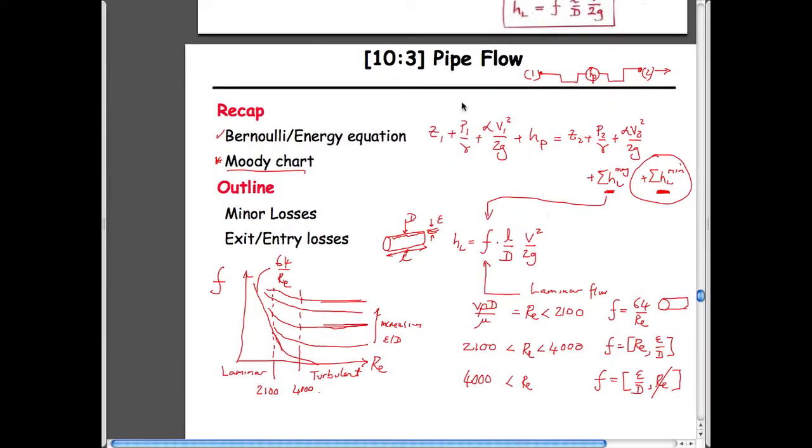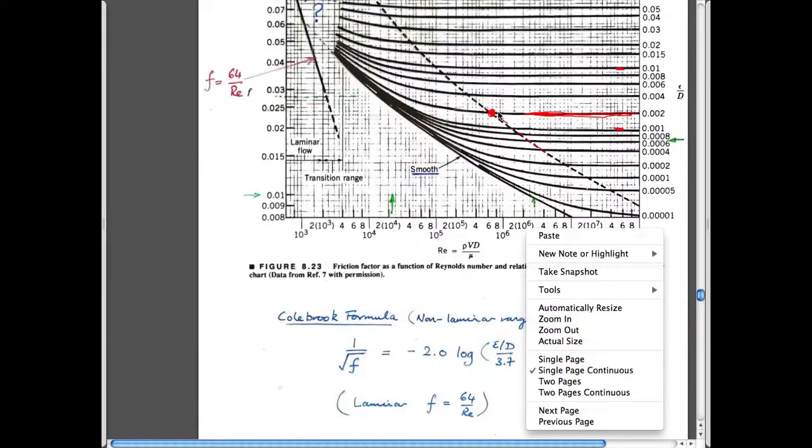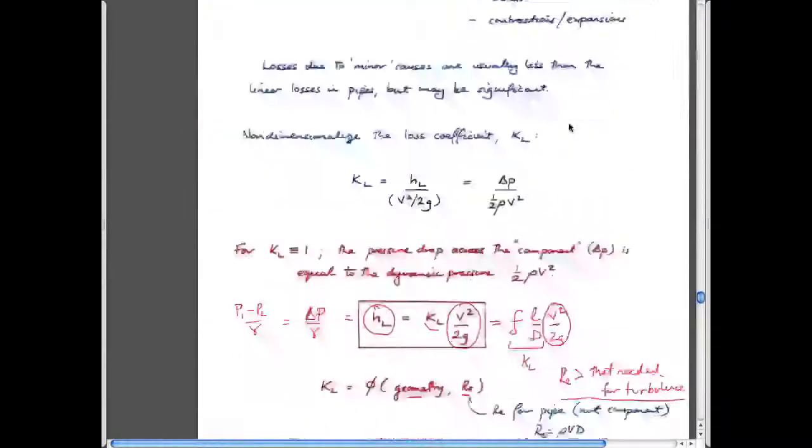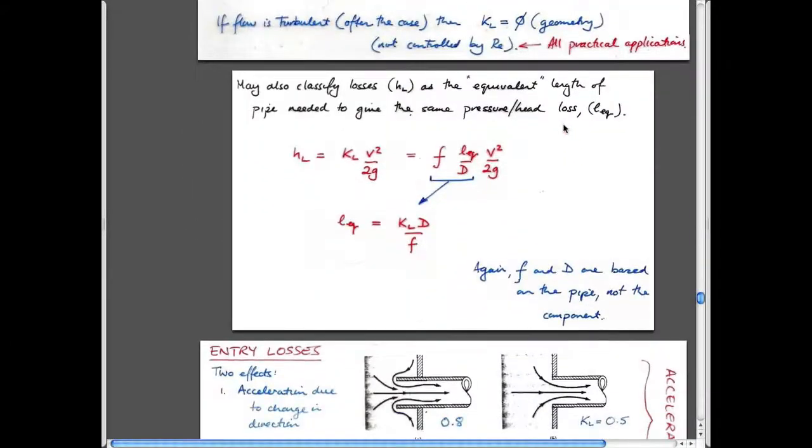And of course, if you're solving this equation where the friction factor is a function of the velocity you're traveling at, and you don't know your velocity yet, then you have to iterate on solving the problem. And so that becomes a bit of an issue. So it's actually very nice if you're in this regime to the right of here because you have a single magnitude of loss coefficient for losses in the pipe and also a single magnitude de facto for losses in the fittings.